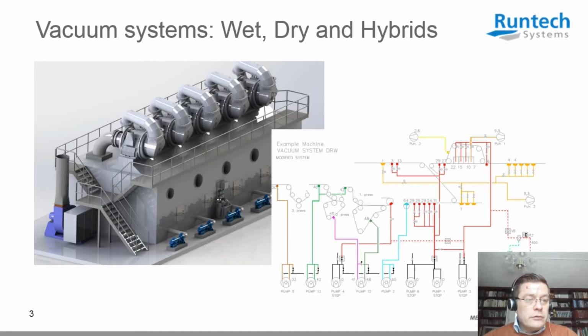Dry turbo systems can then be divided in two: variable speed turbo blowers like EcoPump turbos and constant speed turbos. Overall efficiency, if compared only by figures on paper, is quite similar. Anyway, due to flexibility and better adaptivity, a variable speed turbo blower will be more efficient in the process. We can say that a constant speed turbo blower is mechanically controlled, while variable speed is digitally controlled due to the frequency converter.